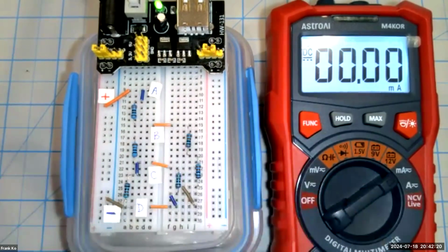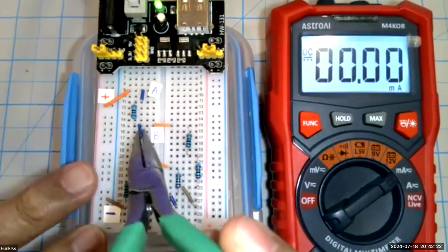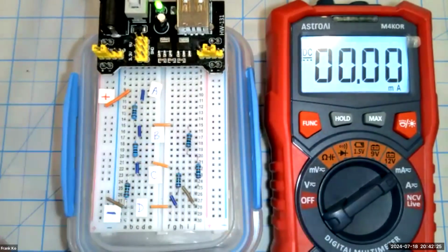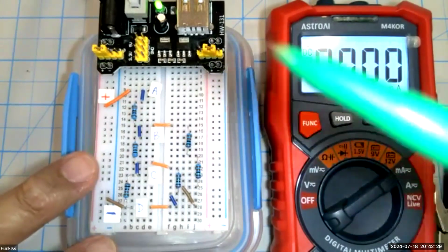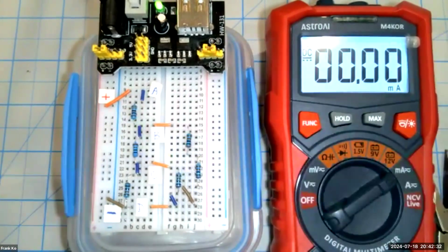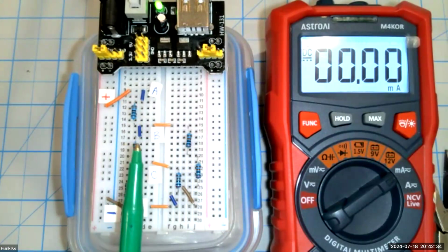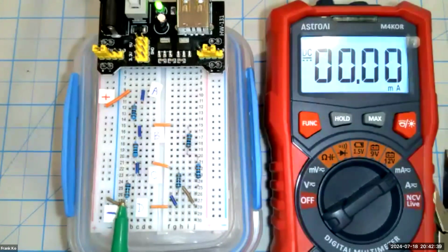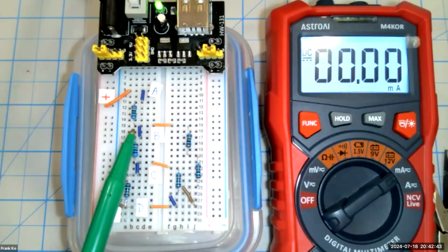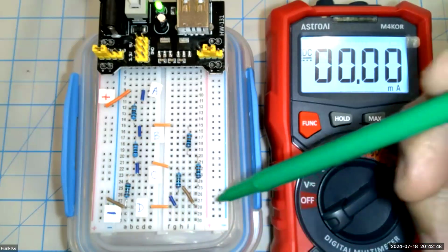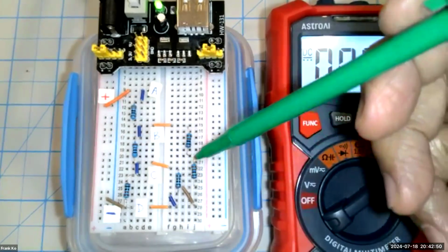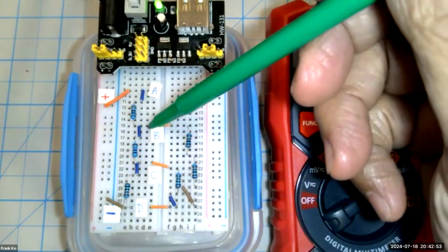So let me rebuild this guy, pop it back down here, push it down. The last current we're going to determine is the current that flows up through R1. Take a look at what happens here. We have currents coming up through R3 and R2. 1 milliamp plus 1 milliamp gives us 2 milliamps through R2. The 2 milliamps going through R2 flows into node B. The R5 current, 1 milliamp, comes up this way to node B.